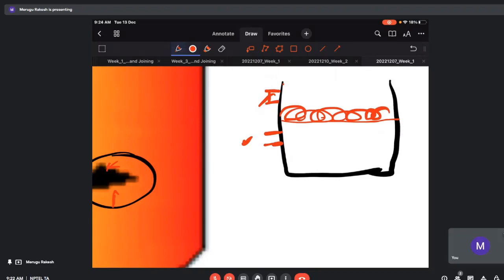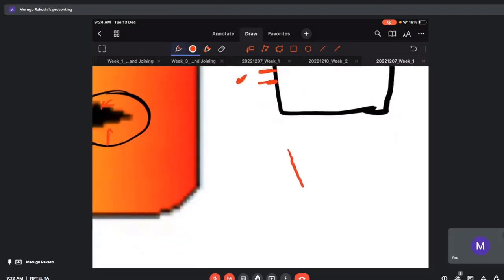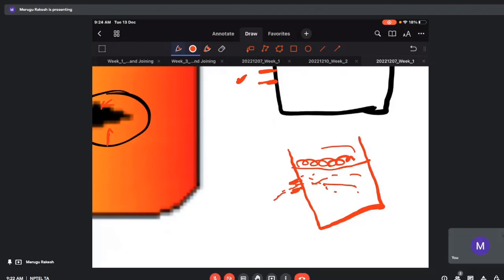so that when the liquid is tilted, when this tundish, whatever we use, is tilted, this slag will be here only, and the liquid metal will enter from this part, so that the slag will get entrapped in the top layer only. Then we can easily clean it off if it is easily cleanable.